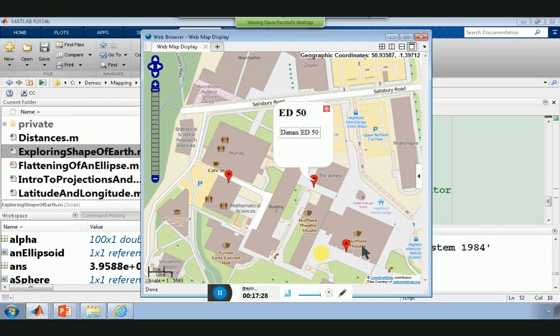Now, one more interesting fact is, until we had these devices that we could hold in our hand that would give us an exact position in latitude and longitude, the way we determined where we were was through a very manual effort of surveying from a reference position. Now, if you defined that datum at some fixed point, that's where the absolute truth is, you could survey from one point to the next, to the next, to the next, and eventually you'd have a point that's relatively close to where you're interested in, and you could measure your relationship to that point to come up with your position. As a result, the positions that have been recorded over time against many of these datums have had opportunities for error.